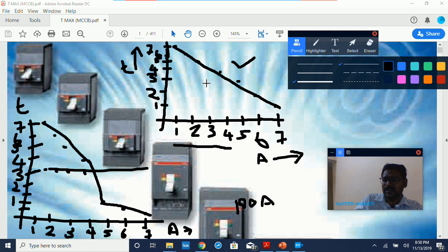If they are asking for a fixed regular 10 into IN, they can go with a fixed breaker also, like an MCB. MCBs trip in fixed type, so 10 times rated current will be fixed. If they want a lesser fixed tripping value, we can go with 3 times fixed. Again, we will discuss this trip unit in a later section today.